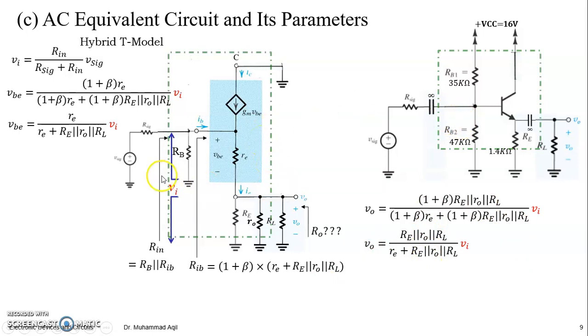Another thing is here you will be having higher input resistance because all these resistances are playing their part to make the input resistance. That's why the common collector has very high input resistance. It means it is a good amplifier as far as the input impedance is concerned. Same is the case, you have a parallel combination of these and in series with this RE, you are having a very low output resistance, a very good stage as far as output impedance is concerned. So these two qualities are very good as far as this common collector circuit or emitter follower circuit is concerned.